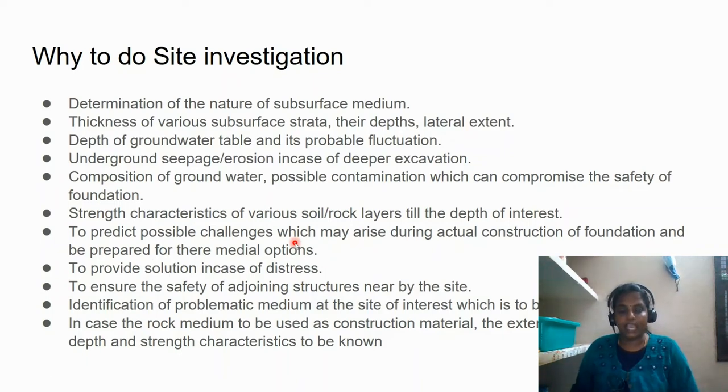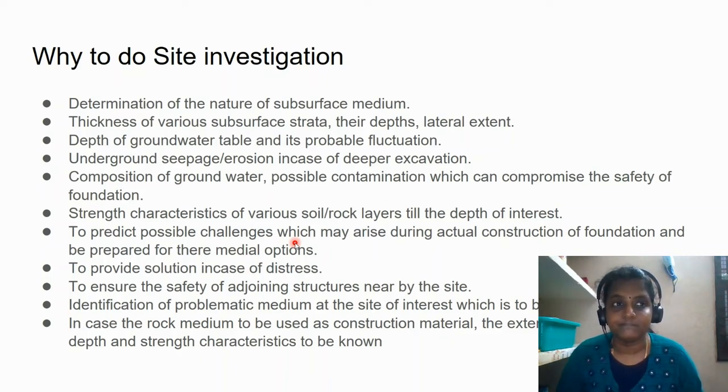We would have thought there could be perfect rock, but suddenly there could be a highly weathered rock, or there could be seepage from the sides. There could be a lake far away, because of sudden rain there could be water seepage into the site. Once water is seeping through, suddenly your site may get eroded, there could be failure happening. There could be quicksand conditions occurring. Imagine quicksand conditions means where you have a flowing of water from the bottom.